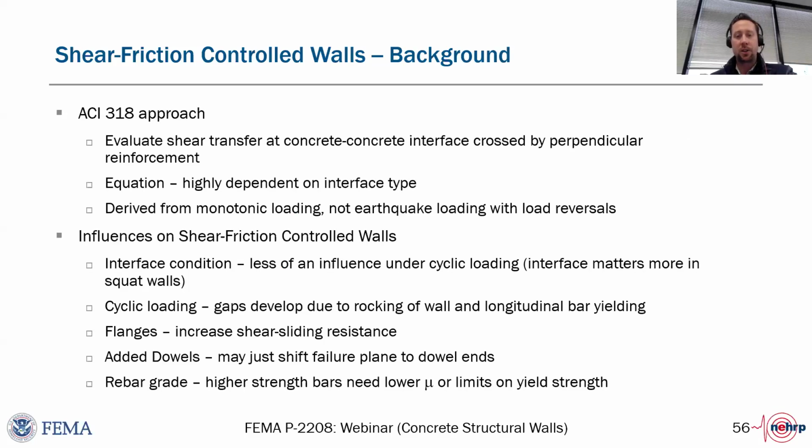The reality is shear friction always was sort of embedded in the standard, but as I mentioned earlier, it really was treated as a force controlled action. And now we actually have some data to give recommendations on the deformation capacities and those things. And in doing that, we also saw that the strength may vary a little bit relative to the shear friction strength provisions that are in ACI 318.